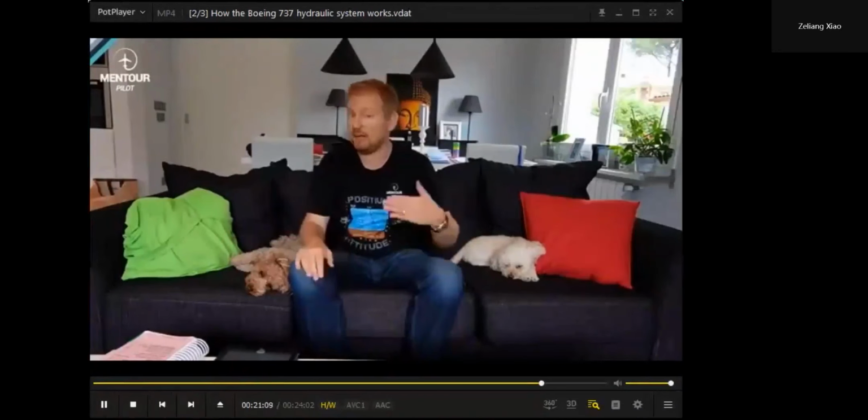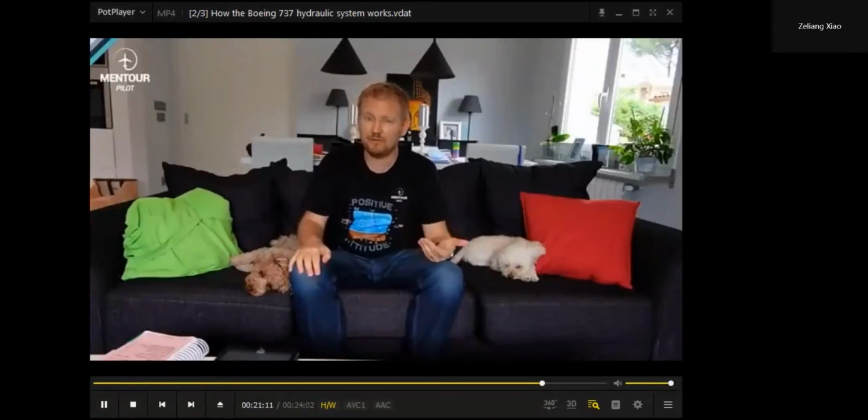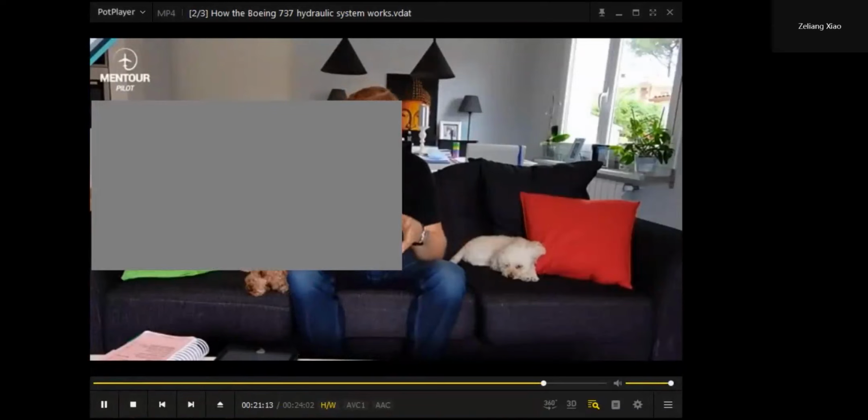It can be flown like this, but it is a bit of a struggle. And remember, once you get down on the ground and land this thing, you don't have any flight spoilers, you don't have any ground spoilers. So the landing distance will be longer, and also crucially, you have neither normal nor alternate brakes.